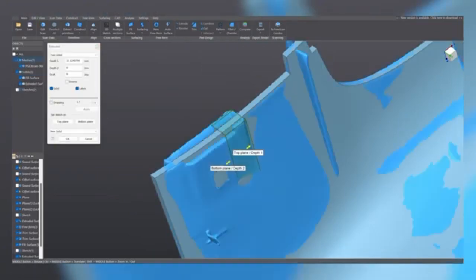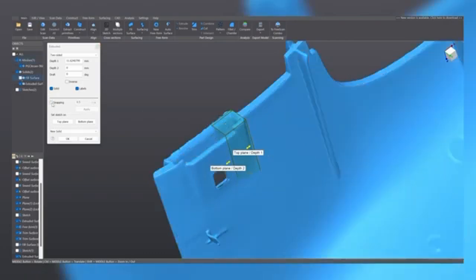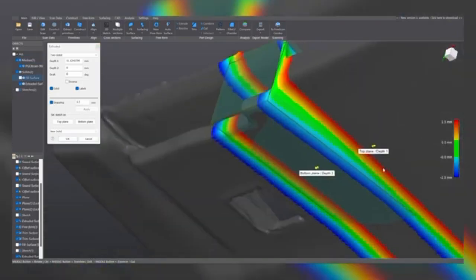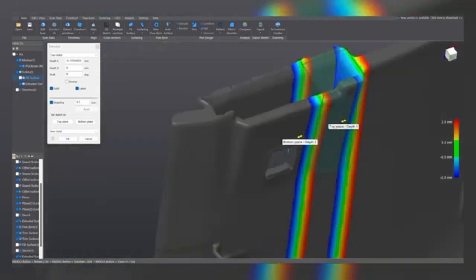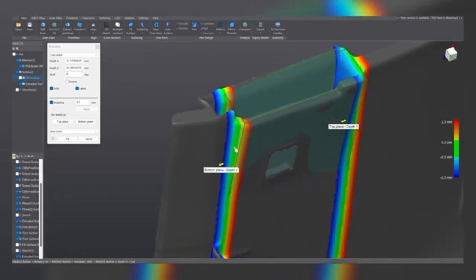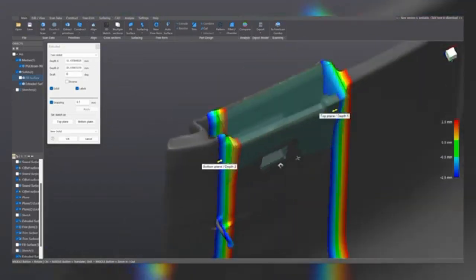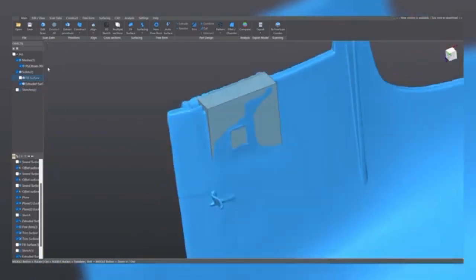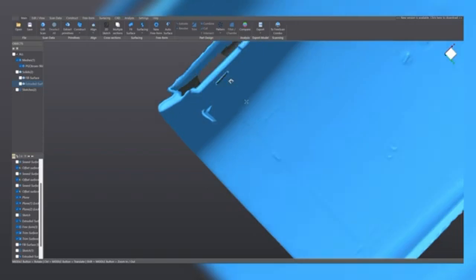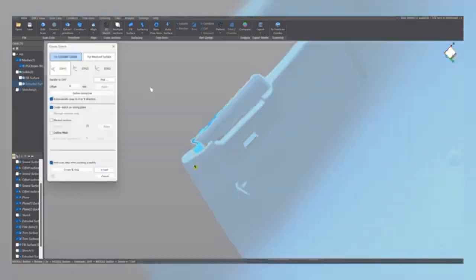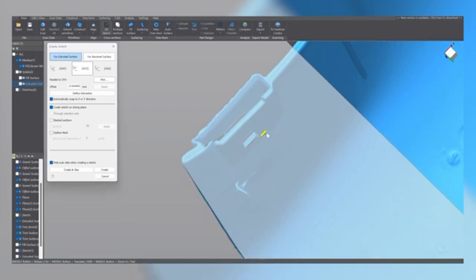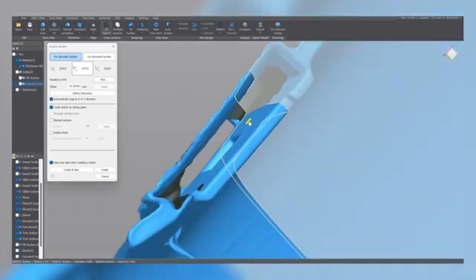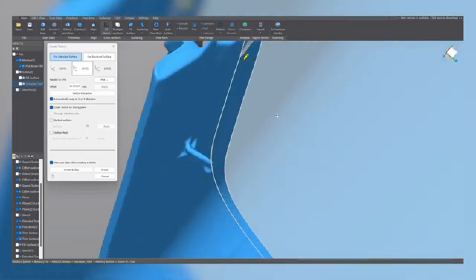Now, with the mesh displayed and the snapping tool on, we can select directly on the mesh the extension of this extrusion. And we are going to use these two walls here. Make sure that new solid is selected and click on OK. Now we have our basic solid, and we are going to tackle now the cuttings. To do the cuttings, we repeat the process. We create another sketch, also in this position, so I have enough information.